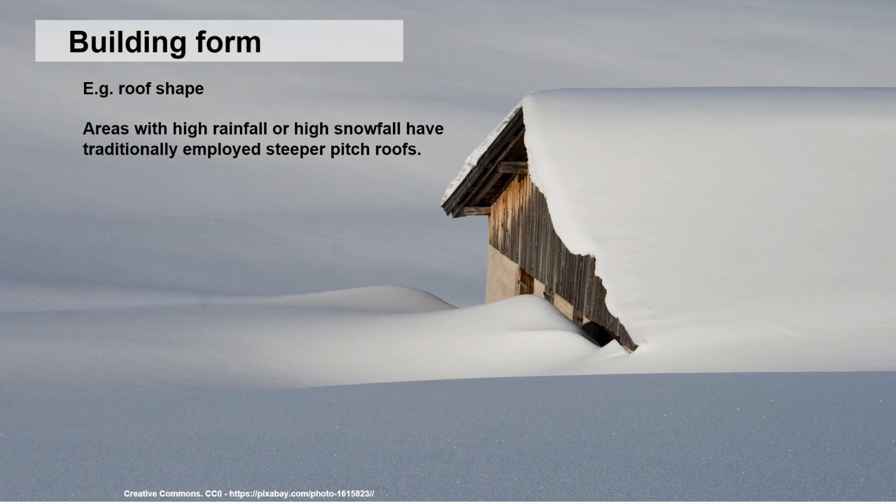Once we've observed this information on site, we can apply that to the form of the building. And if we take an example of an area with high rainfall, we'd probably discover that most areas that experience significant rainfall or snowfall have a steep pitched roof. And the reason behind that is that traditionally we don't really want water to be sitting on the roof.